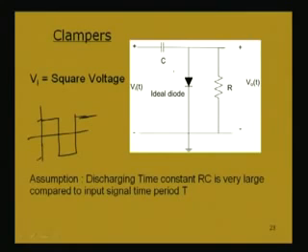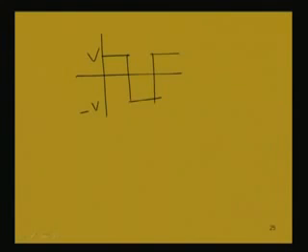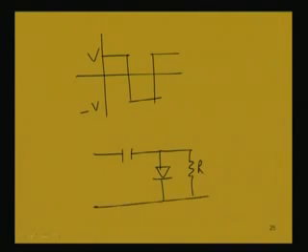Now, this circuit, suppose we are applying a square waveform, what will happen? In the positive half cycle of the signal, the diode will be forward biased. Let us consider this half cycle; suppose we are giving a voltage like this, V, minus V. So, now we have this input voltage, and we have this capacitance. This is the diode and there is a resistance, and this is C.